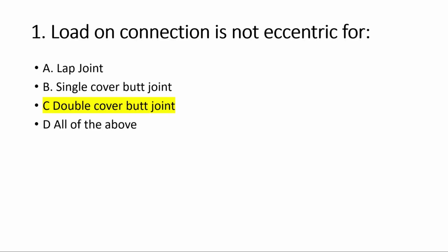The load on connection is not eccentric for which joint? The double cover butt joint. Okay, we know in case of double cover butt joint, eccentricity of force does not exist and bending is eliminated. So it exists in case of lap joint. So option C, double cover butt joint, is correct.